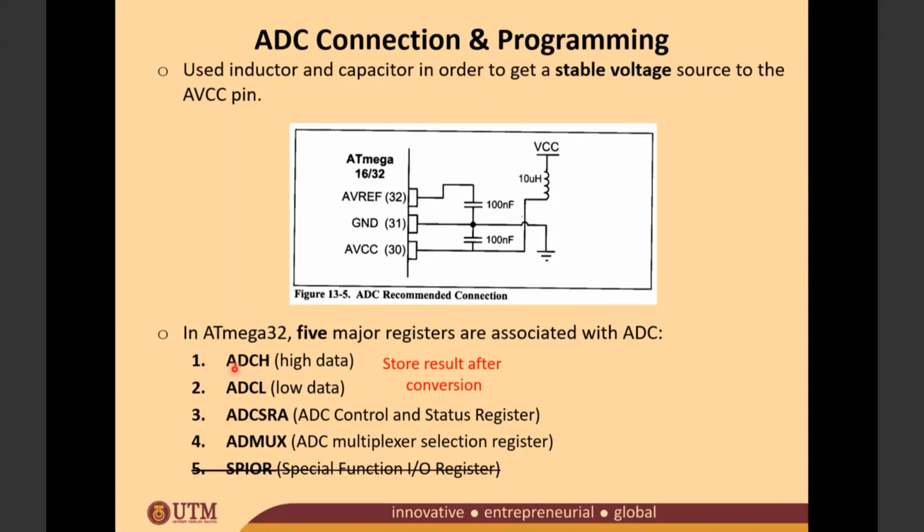Okay, so next we have the ADCSRA. This is the ADC control and status register. This is where you are going to do your settings. All your settings must be done inside this ADCSRA.